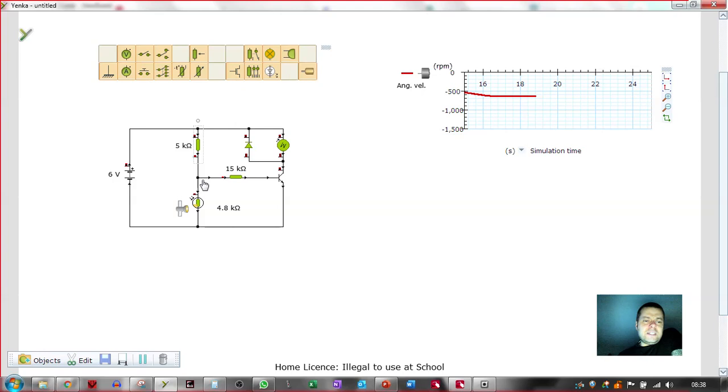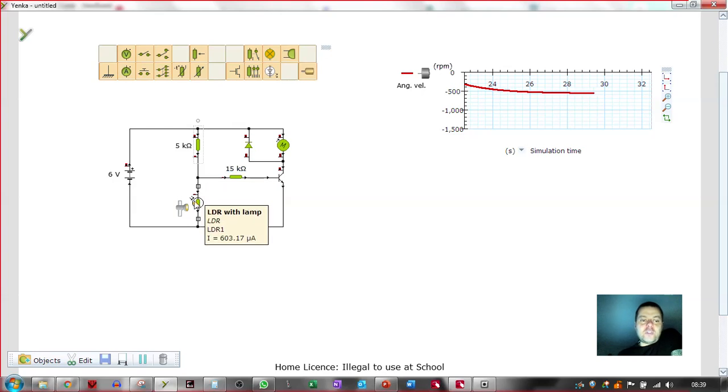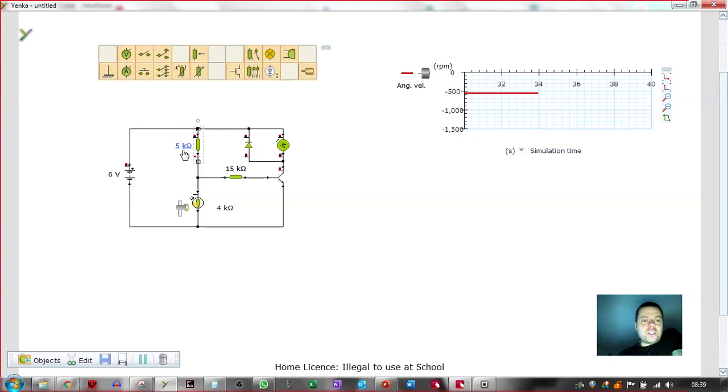The way it works right now is as soon as that light level drops, it would seem that this voltage is breaking 0.7 volts, so it's at 0.698, it's nearly at 0.7 almost immediately. We want to change that balance. We want to change that voltage for that resistance. Obviously we can't do anything to this one because it changes with light level, so it's this one that we can change. So we can change the value of that resistance there, and that will change the response of the sensor. So I'm going to start messing about with